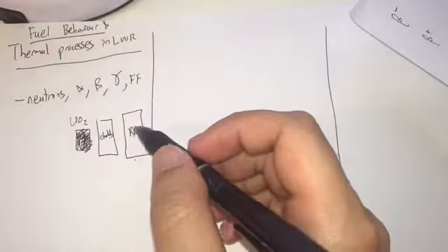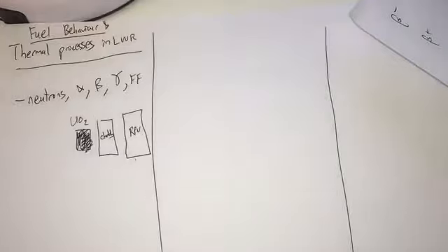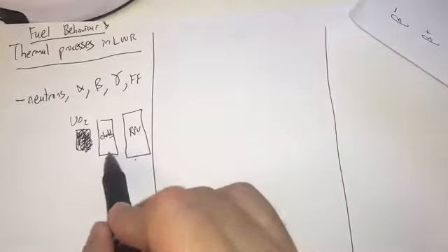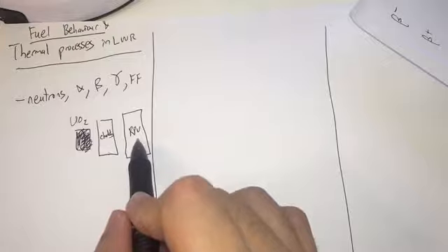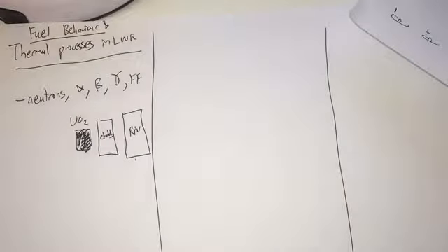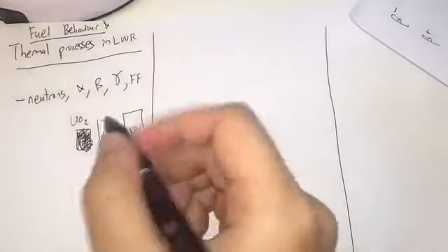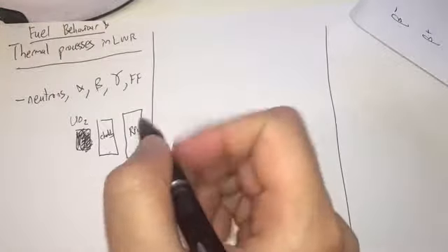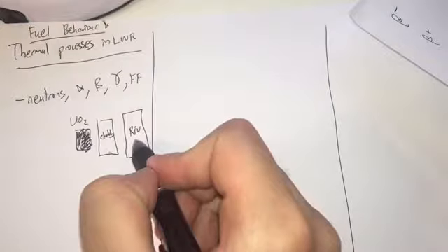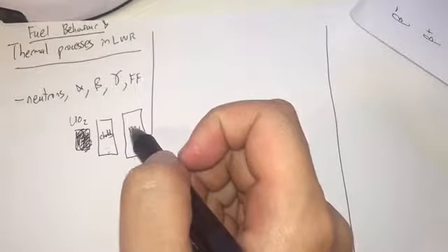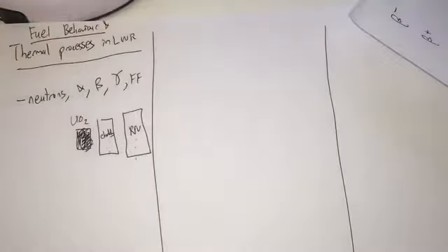Now, previously we've discussed why embrittlement is important for cladding and the reactor pressure vessel, because we don't want them to rupture or leak suddenly. So embrittlement and the stress-strain curve are very important for the cladding and the reactor pressure vessel. But what about the uranium oxide fuel? How does it differ from metals, and what material properties are important?